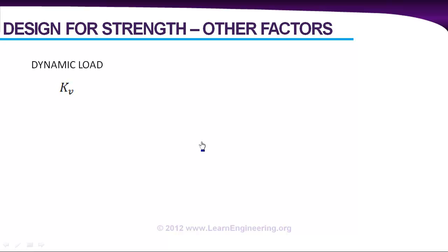First factor is dynamic load on the gear. You know, as gears are rotating, you can hear some sound from the gear. This is because gears are clashing into each other due to the small gap in between. And this effect will increase the load on the gear more than its actual value. That will be known as dynamic load. And there will be a factor to represent that, kV. It will be a function of pitch line velocity.